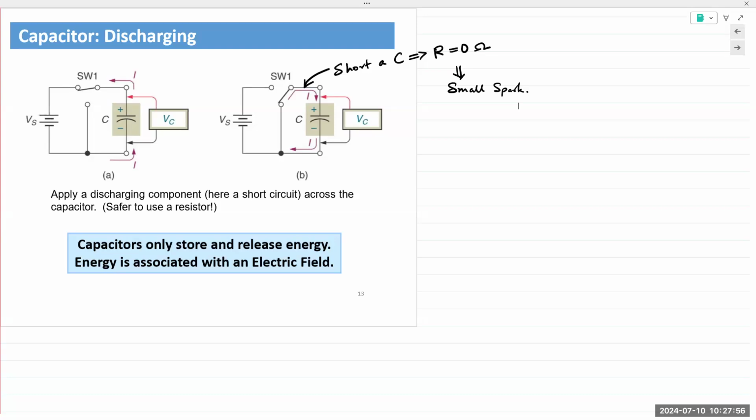there was a short circuit between the cells that were next to each other. And so there was a continuous pathway from the positive end of the battery to the negative end of the battery. And because it was 0 ohms, or very, very low resistance, that battery energy was being released all at once.